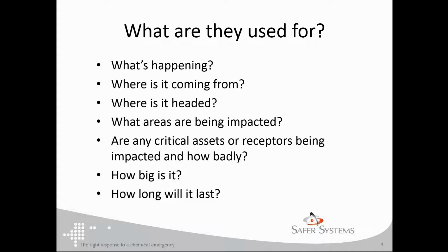So when you're using static weather data, a dispersion model may be run using one snapshot of weather data. In this case, you have wind out of the south moving at 2 meters per second, and you're going to project that plume profile using that data. So the data can be used in risk management planning, emergency response planning, or even in other hypothetical situations where you want to know what might happen given these conditions. But the reality is that it's entirely inadequate to use that static data for emergency response.